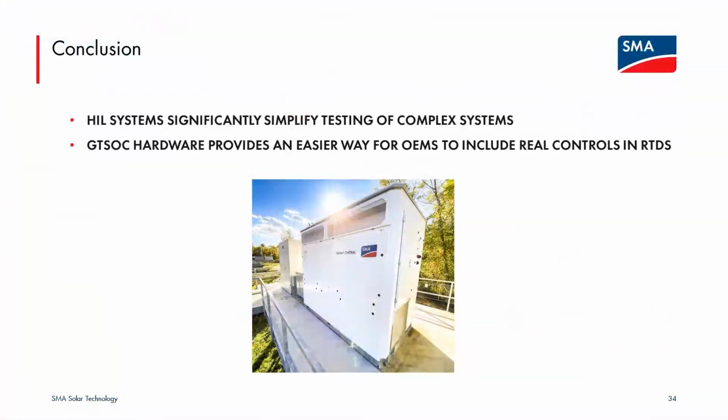So, to conclude this presentation, we learned that hardware-in-the-loop systems significantly simplify the testing of complex systems and thus help to improve quality and reliability of our inverters. Definitely not all tests can be carried out with real-time simulators only, but a lot can be done, and that reduces testing time and thus development and machinery cost.